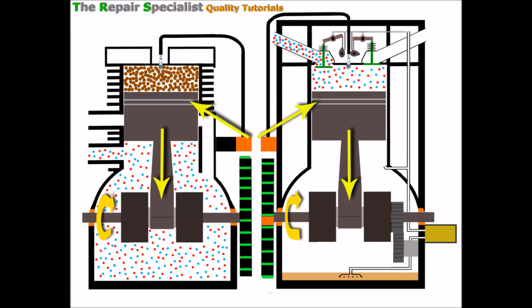And at this point then, we've got both pistons that are halfway down their travel down the cylinder, and that's because each crankshaft has turned another 90 degrees of course. And the four-stroke here is on inlet again, so it's drawing in that air and fuel out of the inlet manifold because the piston's travelling down and it's drawing in all that air and fuel with a suction action. And of course the inlet valve's open at the moment because the timing's correct, and so both pistons continue to travel down.